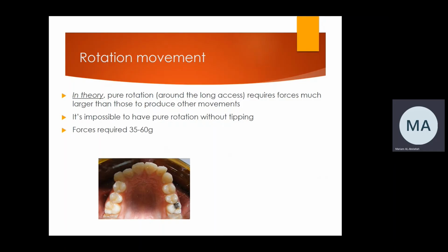So although in theory we need a large force, the range of force for the rotation is exactly the same as tipping movement. It's 35 to 60 grams because at the end it's a cascade of multiple rotational tipping movements.